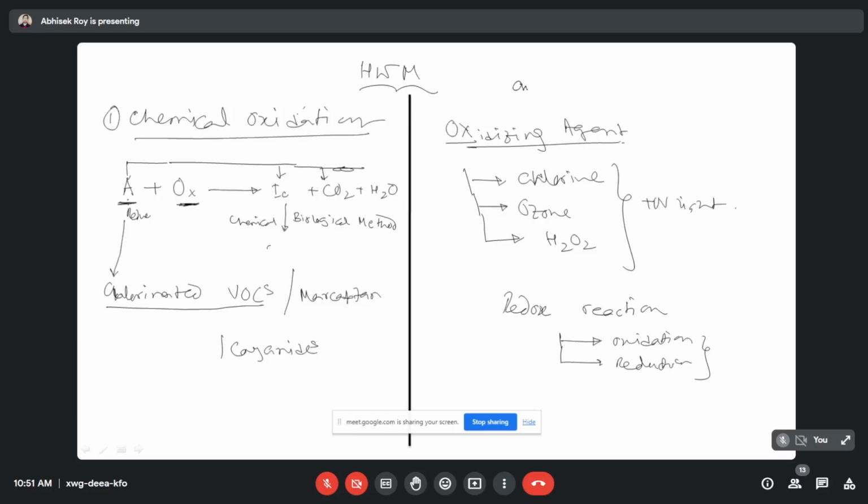You want to target the cyanide present in water, and for that reason suppose you are adding ozone or something else. Now this ozone not only oxidizes the cyanide compound, but it can also oxidize some other organic compounds or other reduced forms of any other compounds. It will oxidize them also. So it is a non-specific one. It will not target simply cyanide only. Okay. So as it is an oxidizing agent, it will normally oxidize the other compounds present in the water also.